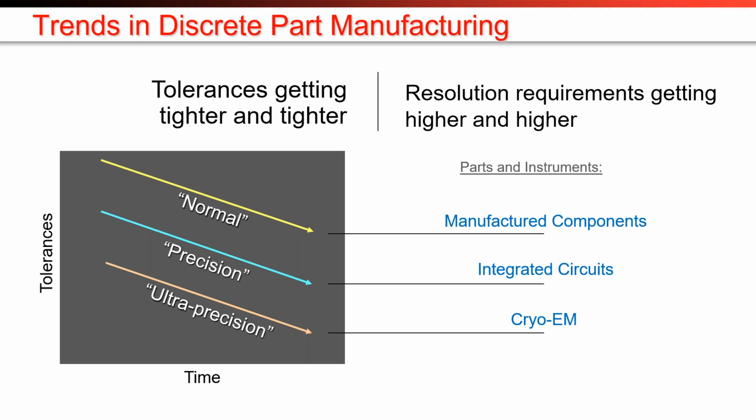And now the most advanced ones in noisy environments will have a combination of a very sophisticated self-leveling air isolation system stacked on top of an active feedback vibration cancellation system. So 2 stages of isolation. That's just another example, something that rubber pads were enough 30 years ago. Now their resolution is so much higher that they need to resort to really extreme vibration control methods to get the instrument to work to its performance specifications. And those are just a couple of examples, and we see it everywhere, really increasing.